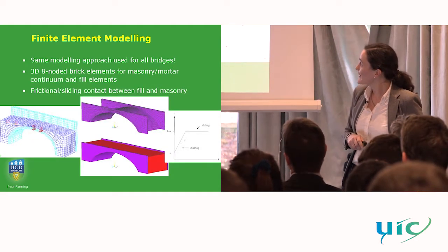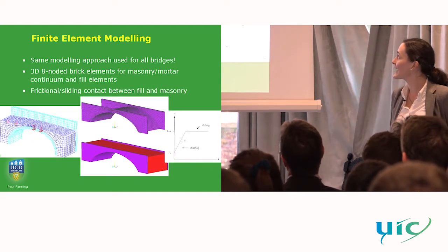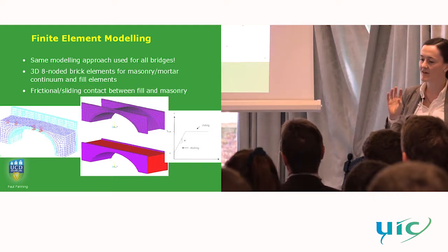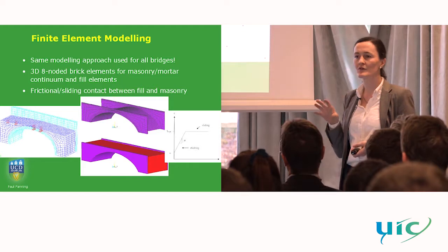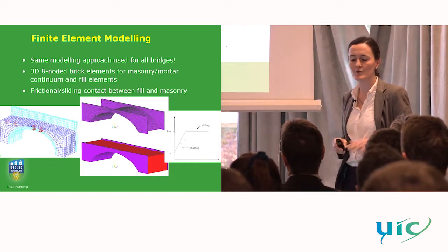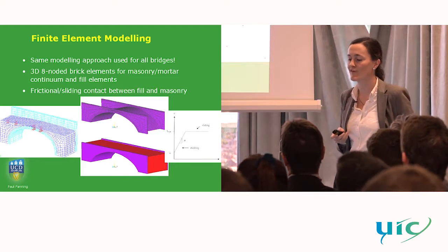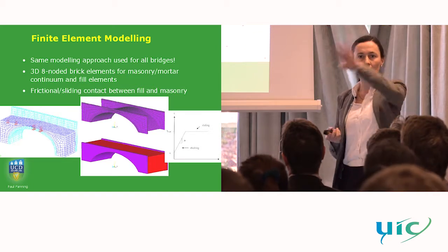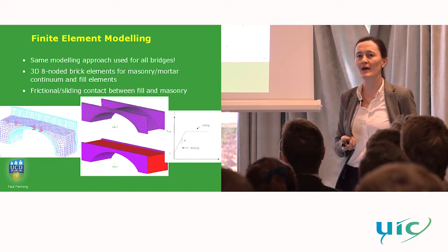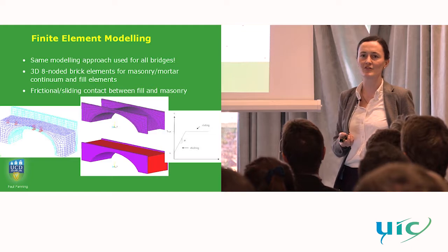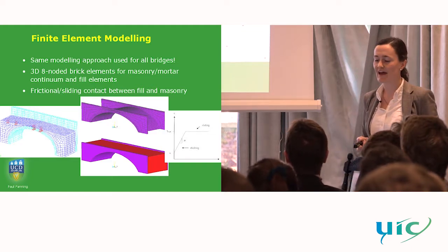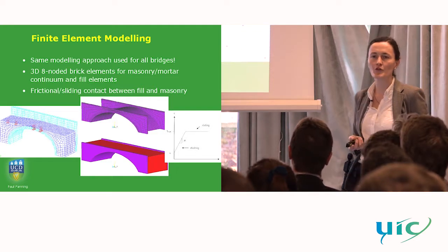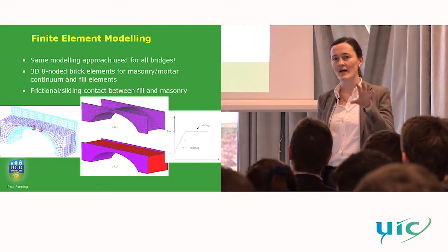So with our finite element modeling, essentially it's a solid modeling approach that we take. We use solid elements, 8-noded brick elements, for the masonry mortar continuum. So we treat both the masonry units and the mortar as a single continuum in the arch. And then the fill elements are also treated as solid elements.